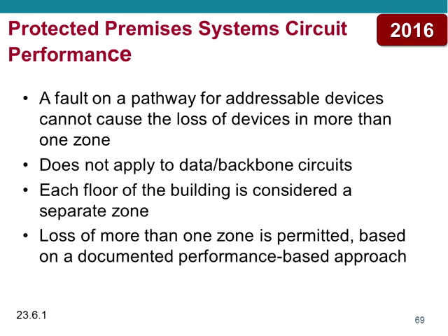And the problem was that what the submitter really intended was that we don't lose more than one zone, okay, the devices in a zone, which is the way it currently reads. And the worry in the 2013 edition was that no one would know what a zone is. Well, if we just look at the life safety drawings like I showed you back in the Chapter 10 changes, you can identify where your paging and signaling zones are. And it's not very difficult to do that. You just need to get those drawings.